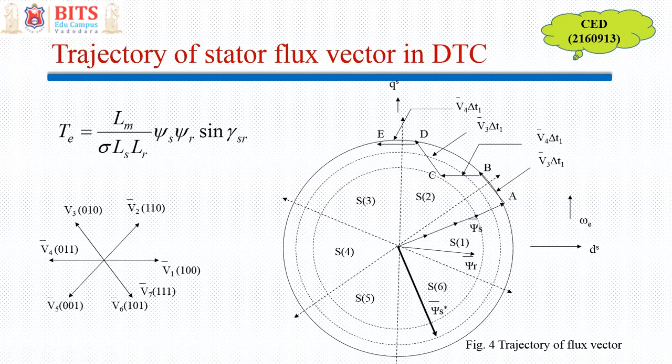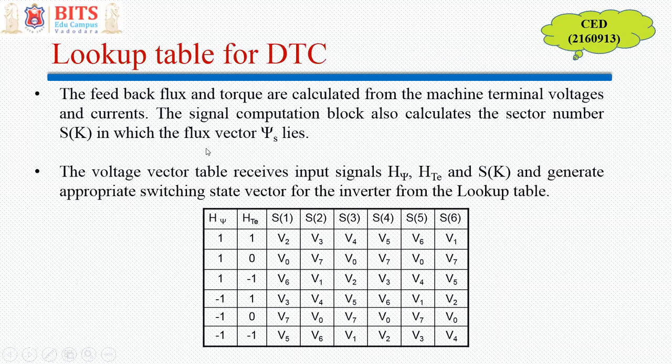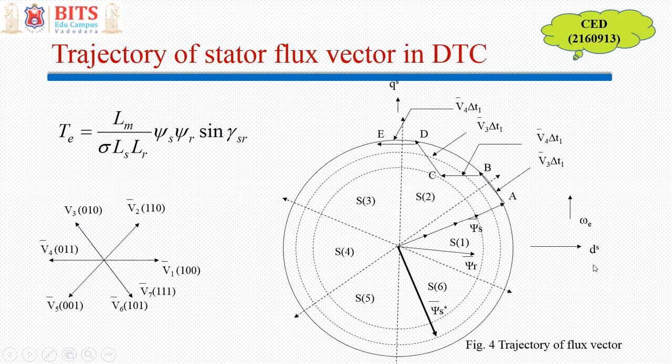So you can have a very decoupled way. Decoupled means depending on your requirement, you can change the value of flux, or decide what to do to increase flux or increase torque. Independently, you can select. So decoupled control is possible without complicated transformation. So this is called the direct torque control approach.